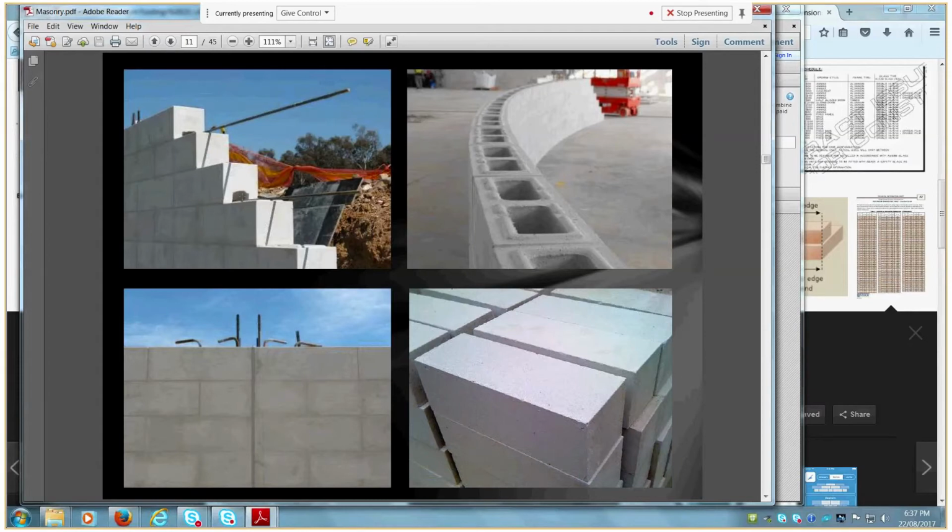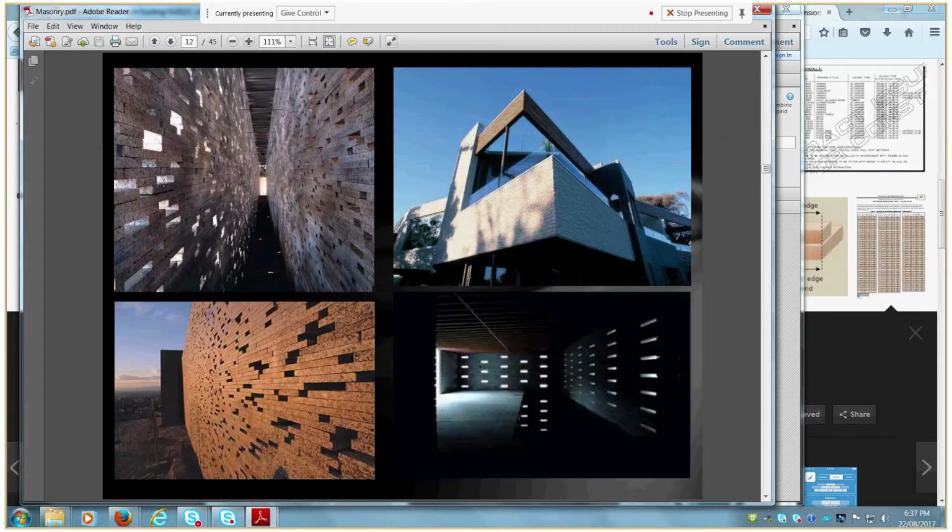You also have horizontal reinforcing to help with any expansion of soil underneath, but it also assists to reduce shrinkage between the blocks. Shrinkage in new concrete blocks can be a significant issue.